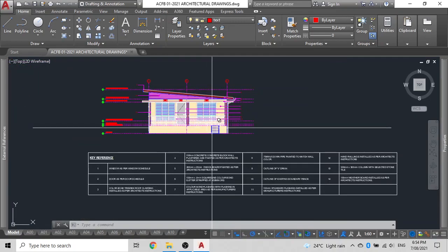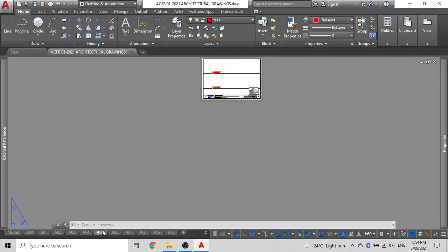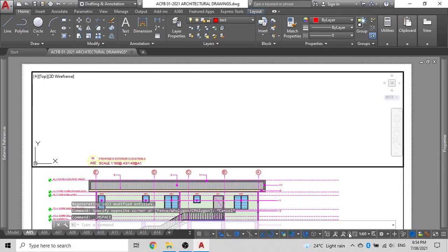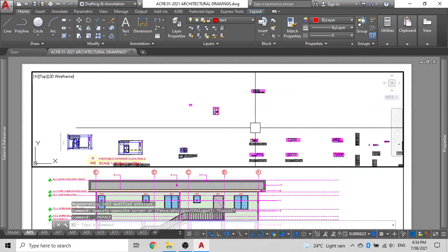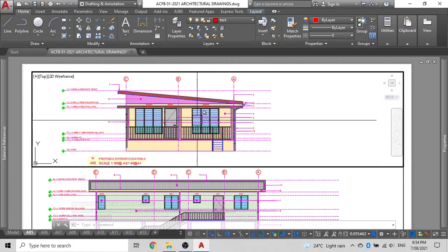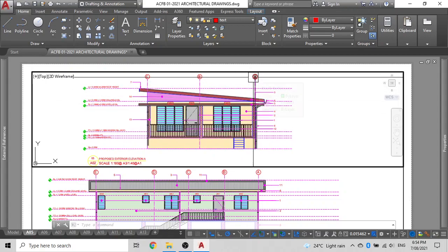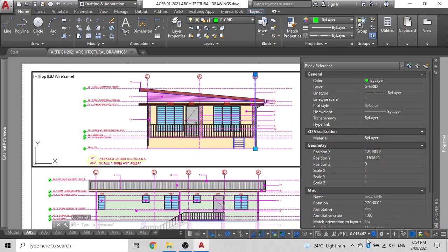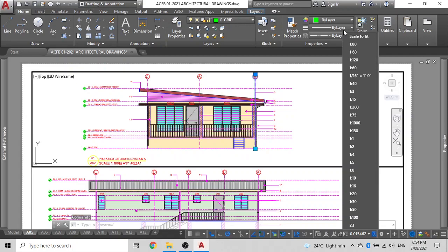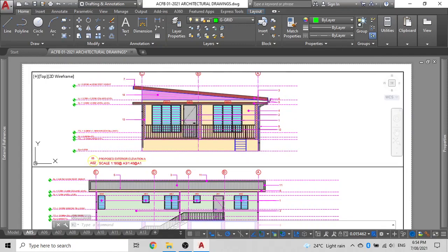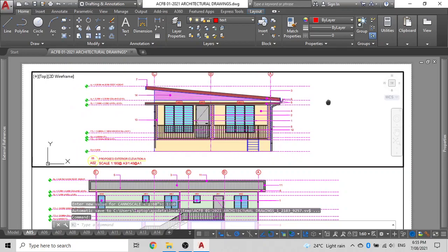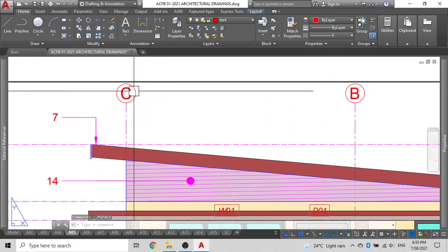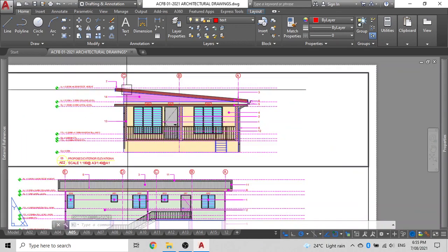Now that you have done that, let's move to the setup side of the elevations. So double click inside your viewport, locate where you had drawn your elevation. Remember to check what scale you are at. If you are not sure what scale you had set up, what you can do is click on one of the objects for that elevation and click over here. It says 1:60. So click on this drop down arrow, that's the scale, and then select your 1:60 scale. Adjust it so it looks to be centered, and double click outside. As you can see that I have more than enough gap inside here.